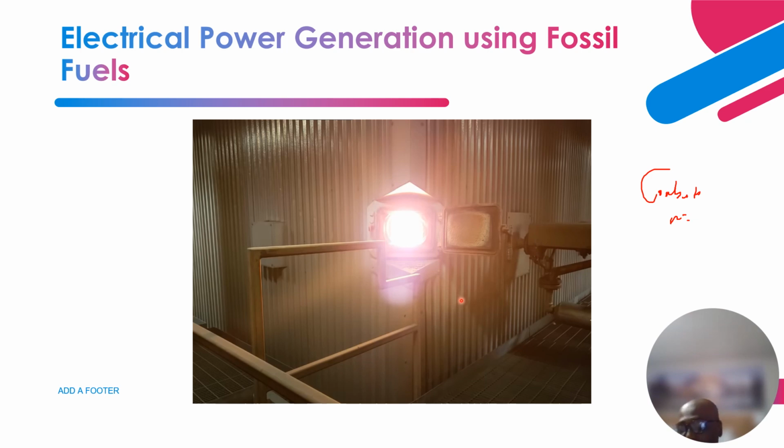The steam rises into the next layer, and from there it goes into different pendants to get reheated. The goal at the top of the boiler is to get the steam as dry as possible, like 98% very dry steam, before it goes into the piping to the turbine.